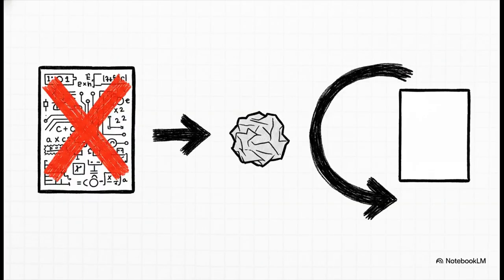And this is the golden rule. You have to remember this. If even one of your assumptions turns out to be wrong, let's say you calculated a negative current for a diode you said was on, your whole solution is junk. It's invalid. You can't just fix that one part. You have to throw the whole thing out, go back to step one with a new guess, and start the analysis all over again.